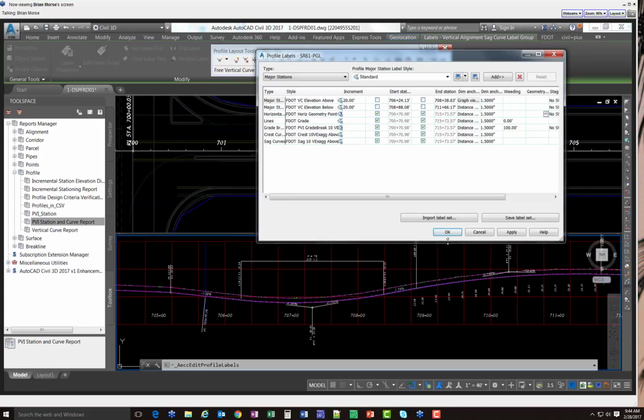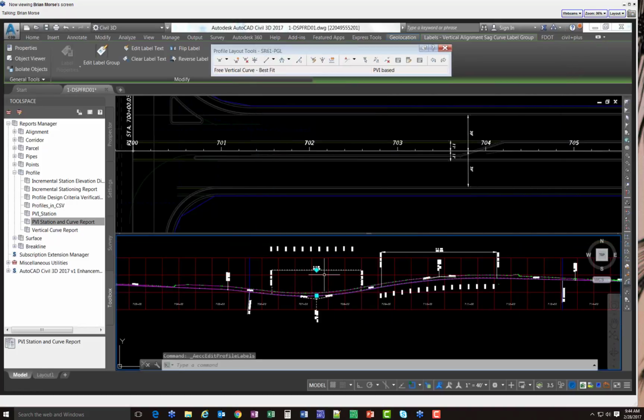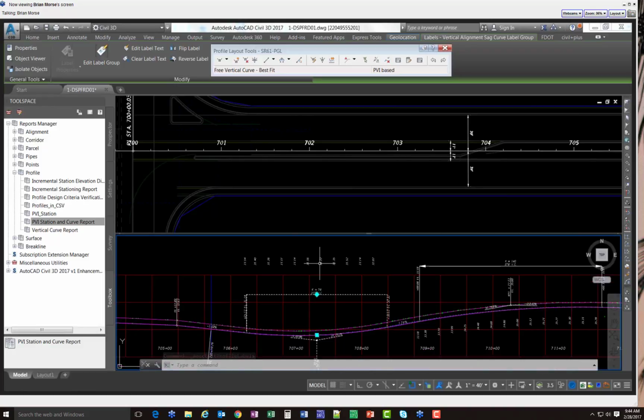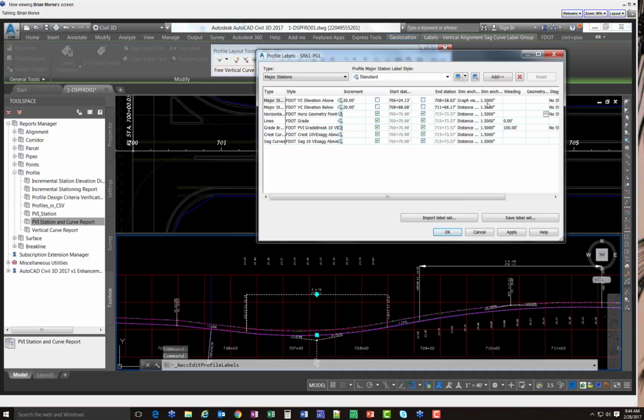And it's like, oh, where did they go? Well, let's just go take a look. They're way up there, graph view top. So if we're going to do graph view top, then we got to do some negative numbers to drive it down here. So what do you say? These are probably about an inch. So if we were to drop this an inch, they would show up here. If we dropped it 2 inches, they would show up right about here. So let's do a -2 on that. Okay, 1.5 to -2. And then we'll see where we get from there.